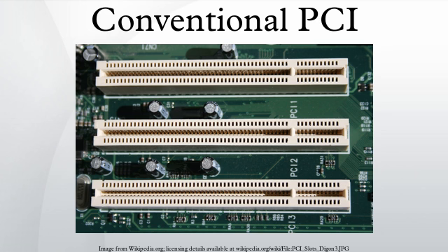1101, dual address cycle, when accessing a memory address that requires more than 32 bits to represent, the address phase begins with this command and the low 32 bits of the address, followed by a second cycle with the actual command and the high 32 bits of the address. PCI targets that do not support 64-bit addressing may simply treat this as another reserved command code and not respond to it. This command code may only be used with a non-zero high-order address word. It is forbidden to use this cycle if not necessary.